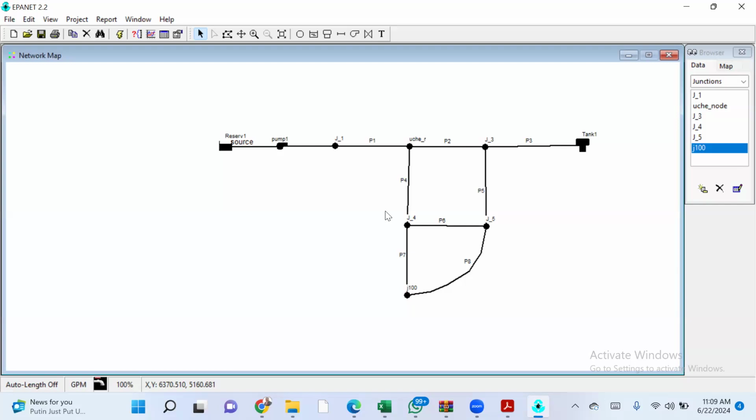No, this is how they choose to design. They do the economical design. Like I said, there's only one city I know that has this design. Ideally, you pump from source to reservoir, then from reservoir to network. But these people, maybe the tank passes through the city. So what they did was to lay a pipe. This pipe will be a big pipe that will supply the reservoir. And as soon as they shut down the pump, with a non-return valve somewhere here, the water will move from the tank to the network. So I want you to accept this network. This is just what they provided for. In our own network, which we did last, it's different.